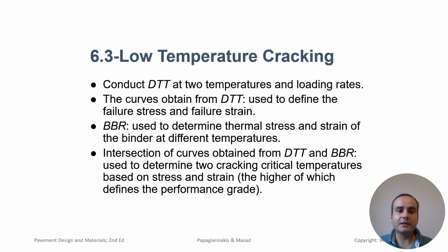Unlike fatigue cracking, which is caused by repeated traffic loads, low-temperature cracking occurs due to the thermal contraction of the pavement. Several tests are used to evaluate the low-temperature performance of asphalt binders and mixtures. These tests can help engineers to select materials that will resist cracking in cold climates.